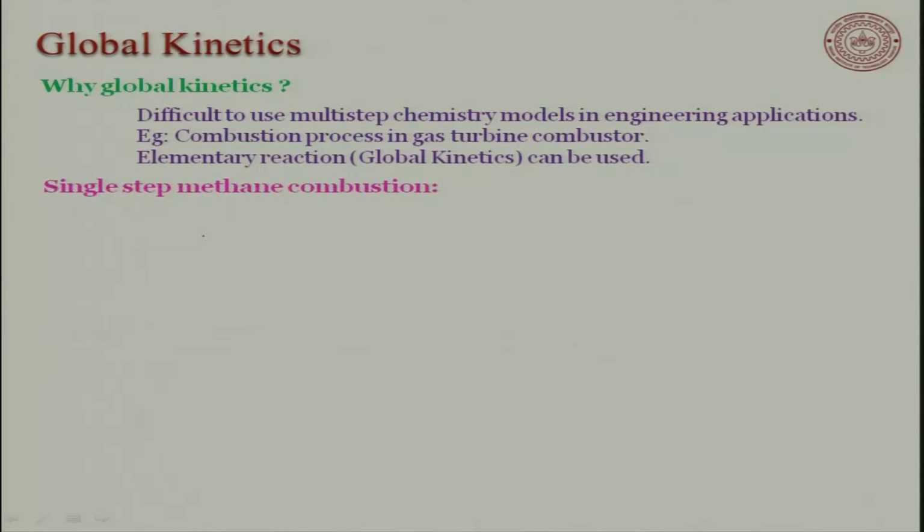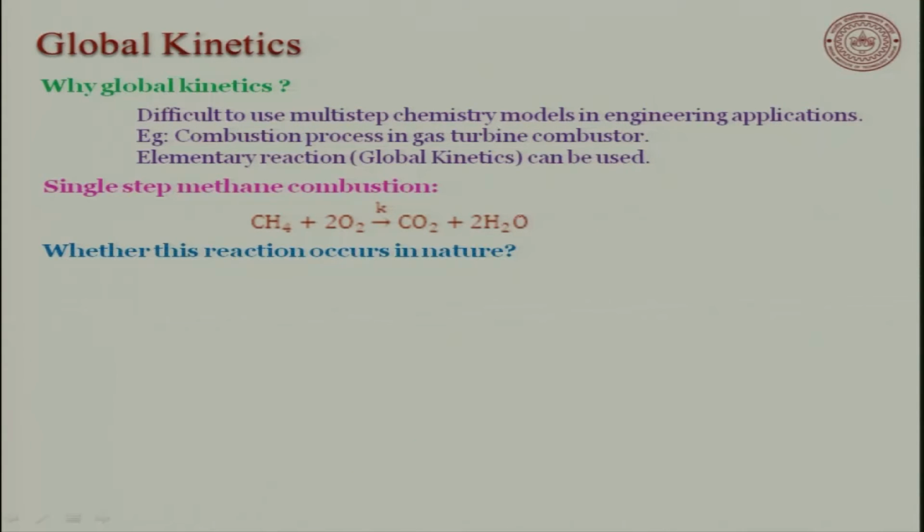What is that? That is basically single step combustion, you can say. People talk about reduced mechanisms, 2 steps or 3 steps, but I will consider a single step as global kinetics. Let us say 1 mole of methane reacting with 2 moles of oxygen, giving carbon dioxide and 2 moles of water. Whether the reaction occurs in nature, certainly not, it is just a model.